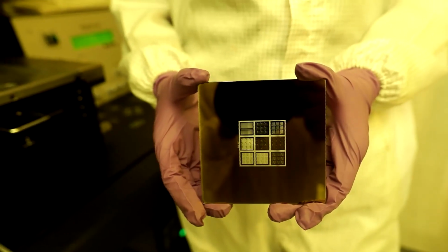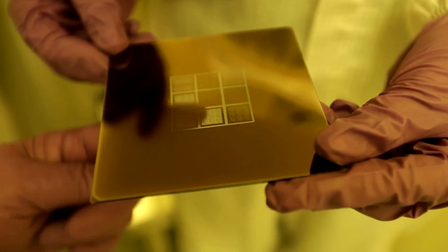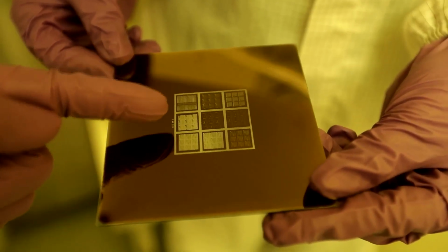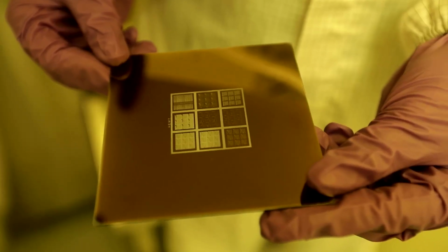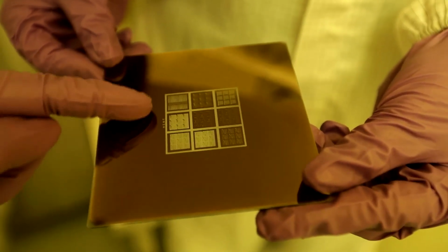Now, let us see the photomask. A photomask is an opaque glass plate with transparent features written on it. Photomasks are made by a fabrication process where a computer-aided design is transferred to a thin layer of chromium on a glass or fused silica substrate.